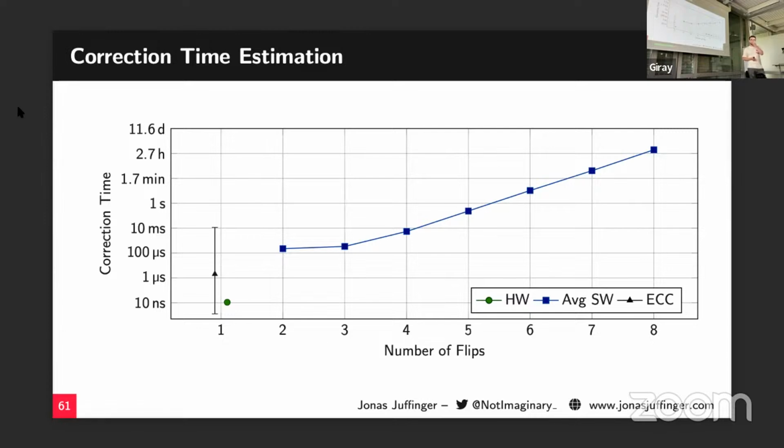So I was curious: in the doomsday scenario, I have 8 bit flips and it takes like 5 hours or 8 hours to fix it, right? So instead of facing that situation, is it possible I do memory scrubbing using MAC every hour, for example? Totally. And then I will never see 8 bit flips, for example. Yes. You could easily implement this by just having a kernel thread that activates once per hour and reads the whole memory. It's like 20 lines of code, basically. And then the chance is really low that you see 8 bit flips.